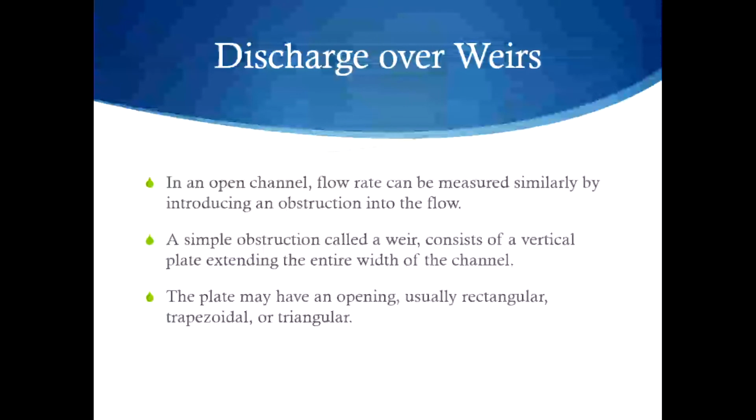So imagine this. Imagine you are seeing a river and you are wondering what is the flow rate the river is going through and at what velocity. And since we don't have the cross-section area, if we have a river, we cannot find the cross-section area of the river because it varies along the way. So we can create a weir with a known cross-section area to calculate the parameters of the flow. If we create a rectangular weir, we will force all the flow to go into that rectangular section, and then we can calculate an h and therefore calculate the velocity, flow rate, etc.